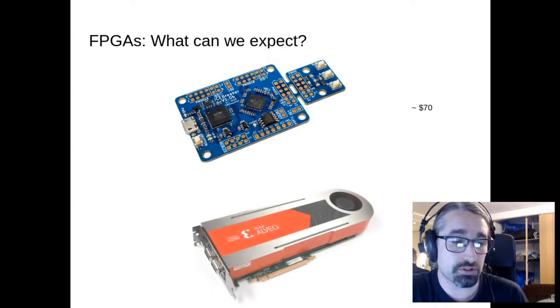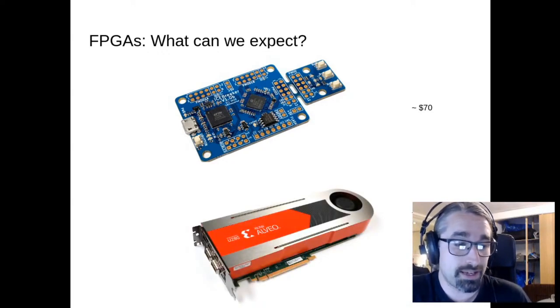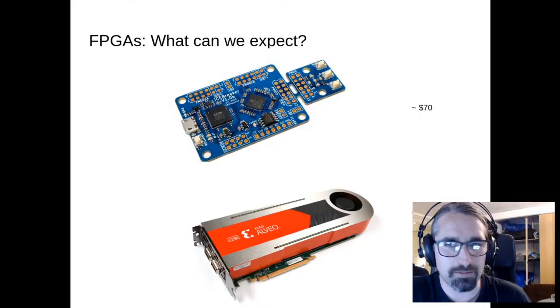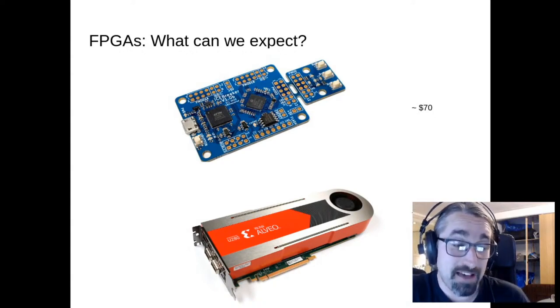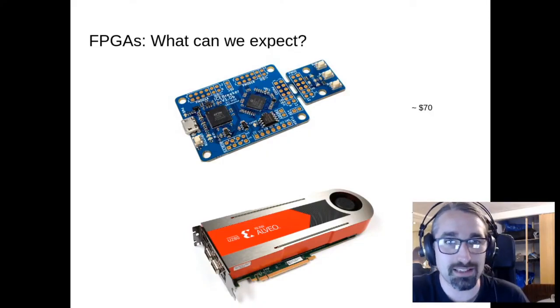But then you have also this type of beast, which is PCI Express based with, I think it was, 8 gigs of HBM2 memory with half a terabit per second bandwidth. Well, a pretty big fan, one must say, and transceivers that can go to hundreds of gigabit per second.